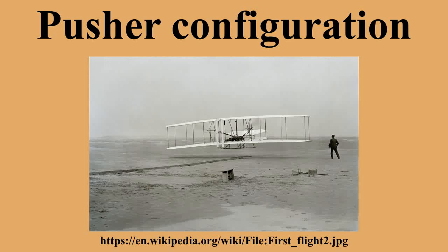Engine cooling and exhaust. In pusher configuration, the propeller does not contribute airflow over the engine radiator. Some aviation engines have experienced cooling problems when used as pushers. To counter this, auxiliary fans may be installed, adding additional weight. The engine of a pusher exhausts forward of the propeller, and in this case the exhaust may contribute to corrosion or other damage to the propeller. This is usually minimal, and may be mainly visible in the form of soot stains on the blades.